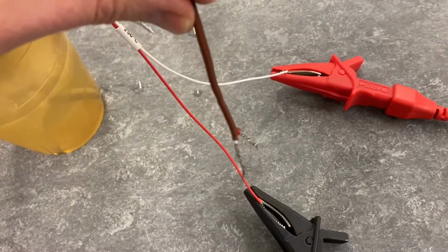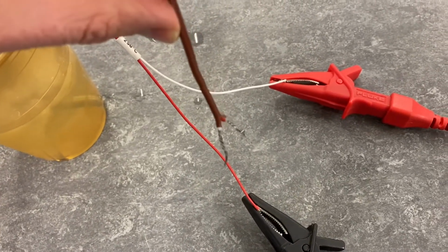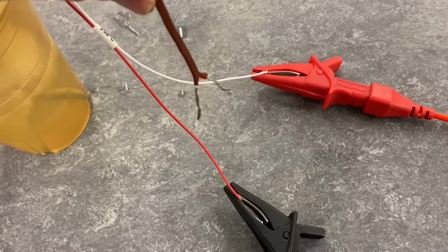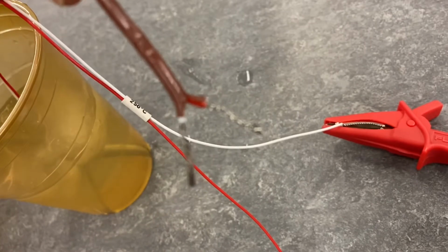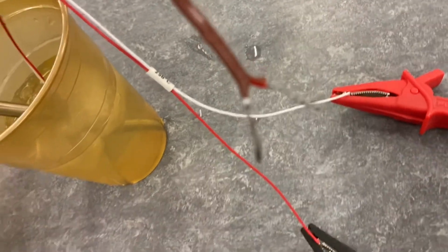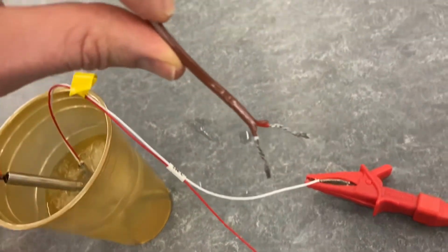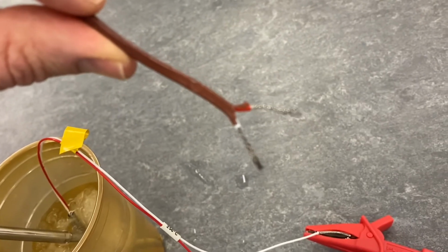All right, so one other thing I wanted to show is that I've got a thermocouple and a 2-wire RTD in front of us. The 2-wire RTD has the alligator clips connected to it right now. But if you look, a thermocouple will always only have 2 wires. And right there I have a type J thermocouple. It's got a red and a white lead.